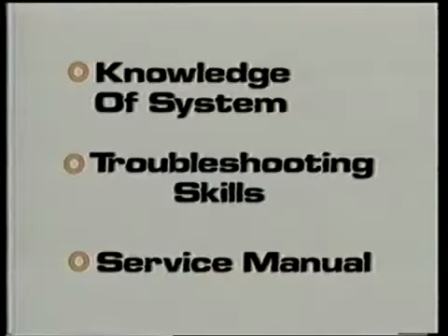In summary, to quickly diagnose electronic fuel injection system troubles, you must have a knowledge of the system, you must know how it is supposed to function, you must use basic troubleshooting skills, which will be demonstrated in this video, and you must use the service manual. The service manual will give you the exact specifications, fuel pressures, flow volumes, and electrical values particular to the specific make and model of car.